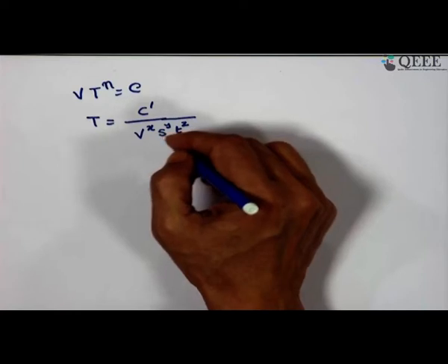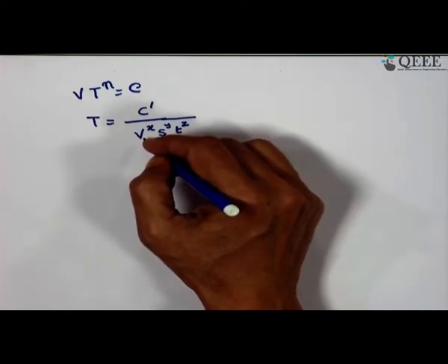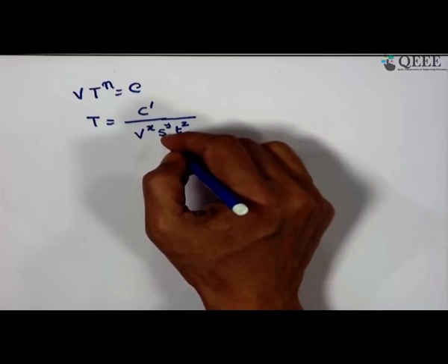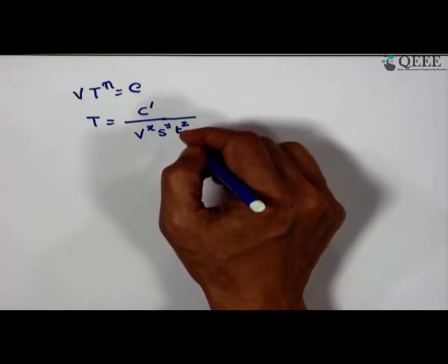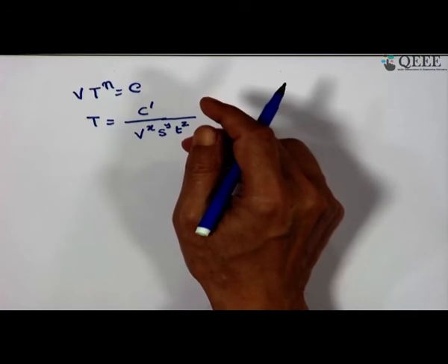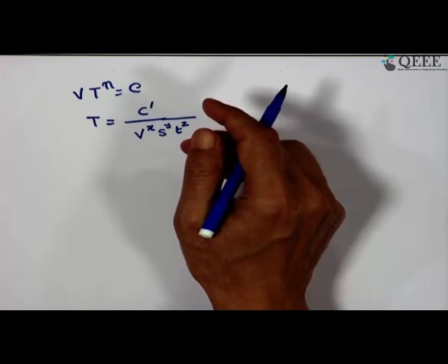You can imagine the effect of velocity on cutting temperature and the effect of feed on temperature is more prominent than the effect of depth of cut. Depth of cut does not influence much, because as we increase the depth of cut, force increases, and force into velocity means energy, but the thermodynamic load per unit length of the cutting edge remains the same. That means the specific load does not change.